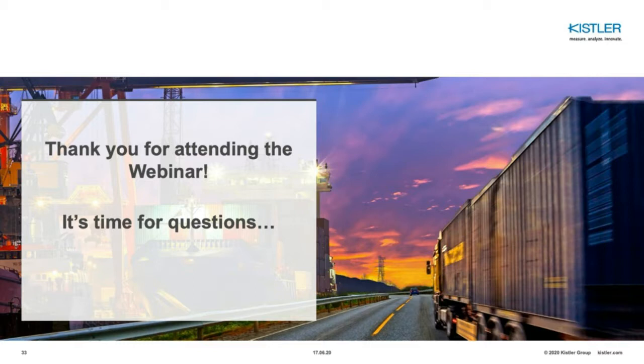And in addition, what you need to understand about the quartz-based WIM technology, and that's true for all quartz WIM sensors from Kistler, they don't show any degradation over any kind of load cycle. So these sensors are extremely stiff, and the quartz disc has absolutely no fatigue inside the sensor. So from this point of view, the sensors would last forever.